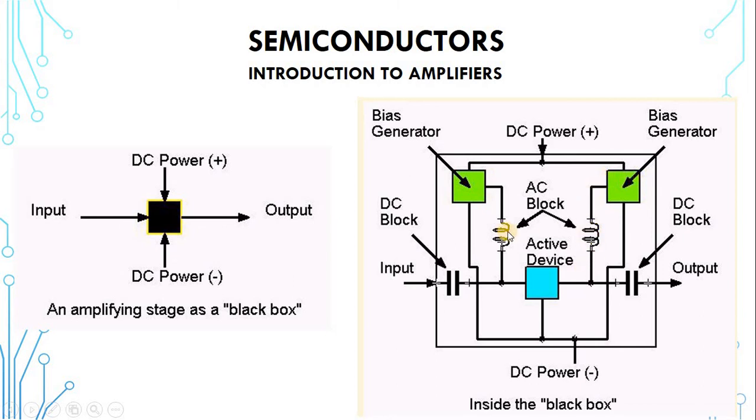So by the application of the coils here in this way, it blocks any AC ripples that may be in the power supply to our amplifier. Another way of saying that, it filters out any AC component in the power supply so that we can be sure that very close to pure DC gets to our amplifier to properly bias it.